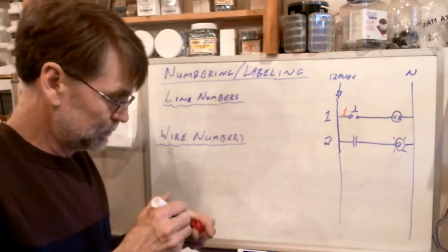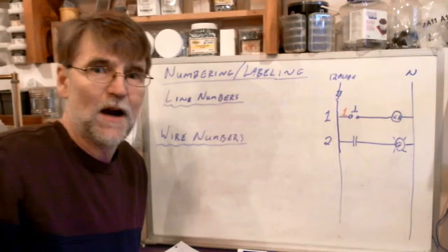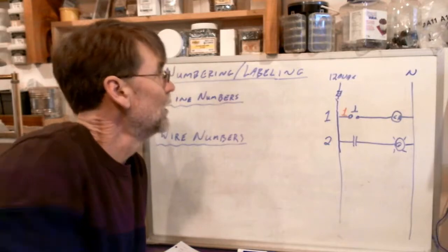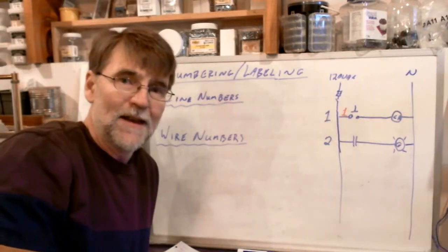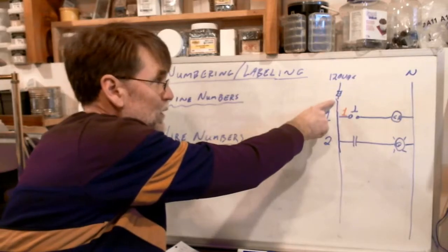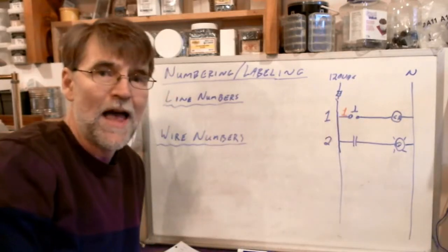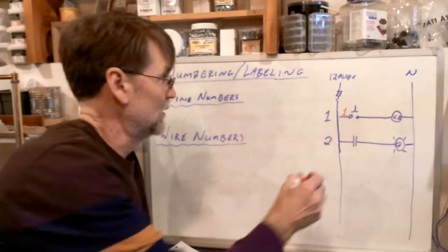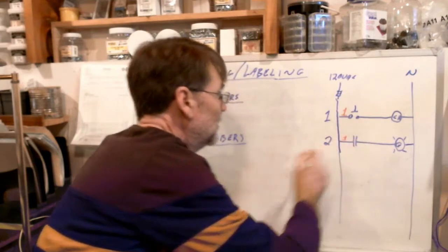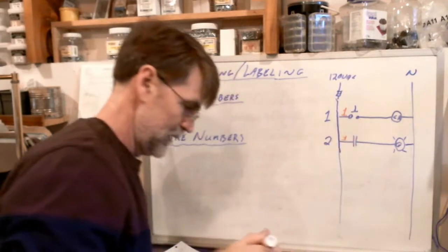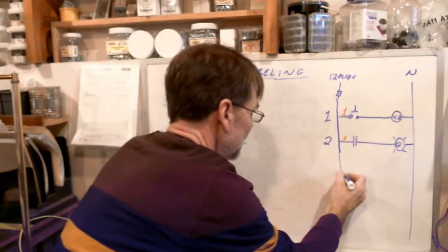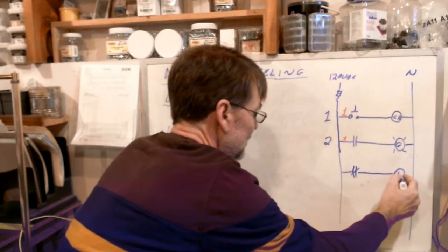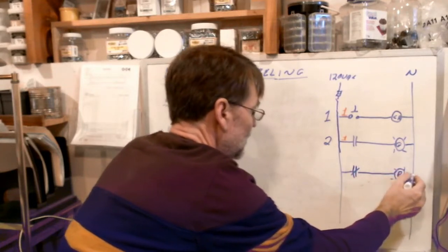So the question is, when is this wire going to be 120 volts above ground potential? And the answer is the whole time the lab is turned on. The lab station is turned on, the circuit is energized, we close that switch right there, there's 120 volts at that wire. Where else is that true? At the beginning of every single rung, which means this wire right here is also wire number 1. If we drew a third rung on our diagram, we'll put a normally closed contact there, make that a red light.